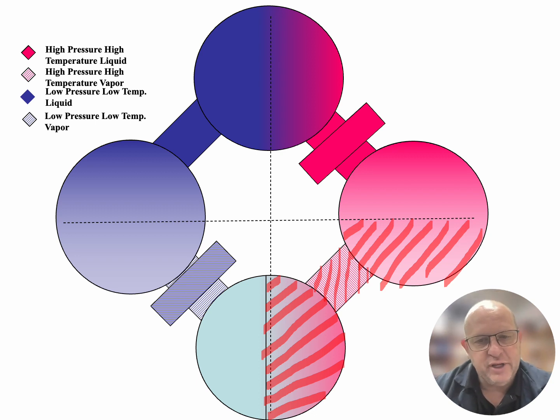Now, going back to our analogy of water, as the refrigerant is coming into the compressor, it compresses it. Vapor in, vapor out. High pressure, high temperature vapor is going to be pushed into the condenser. Now, the purpose of the condenser is to take the heat that was absorbed in the evaporator and to remove that heat from the system. Now, water, if you add heat to it, will turn into steam, vapor form. And then as you remove heat from the water, the vapor will turn back into a liquid form.